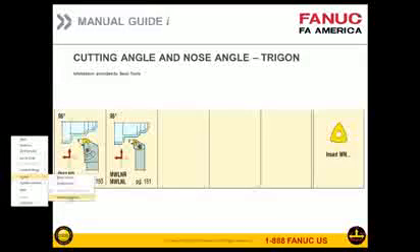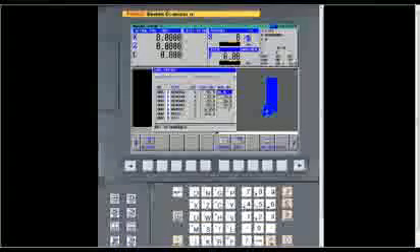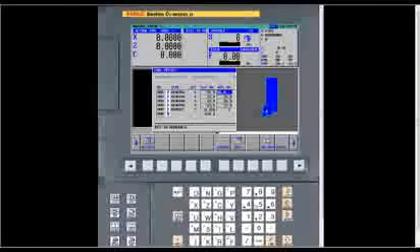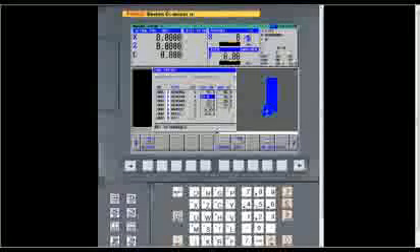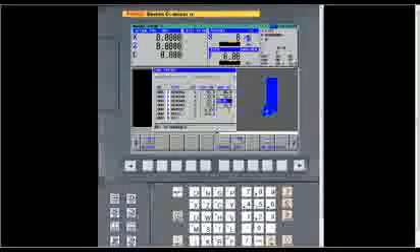Now at this point, we'll go back to NC Guide. So that's the type of information on these first four. I've got turning tools, so 35 degree with a 93 degree cut angle, and 93 degrees with a 55. Those are all my turning tools. Basically a rough, a finish, and a semi. With those tools, you ought to be able to get into almost anything.